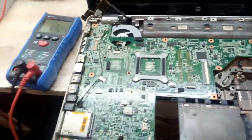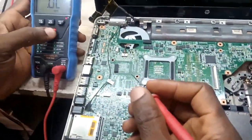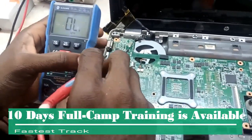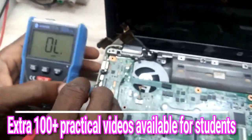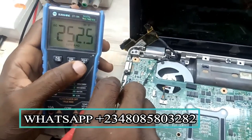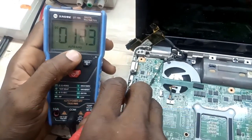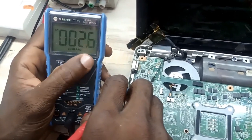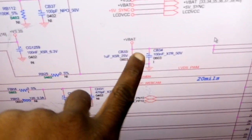So let's check the available and missing voltages, which is the first one. Starting from the lower part here, I should have 3 volts, or let me start from the first pin at the top. So pin number 1, 40, 38, 39, what do we have? We have 5 millivolts. 5 millivolts. Here I'm supposed to have 19 volts VBAT, adapter and battery voltage.